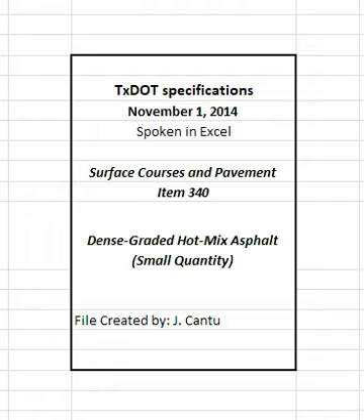4.9.6 Ride Quality. Use surface test type A to evaluate ride quality in accordance with Item 585, Ride Quality for Pavement Surfaces, unless otherwise shown on the plans. 5. Measurement. Hot mix will be measured by the ton of composite hot mix, which includes asphalt, aggregate, and additives. Measure the weight on scales in accordance with Item 520, Weighing and Measuring Equipment.